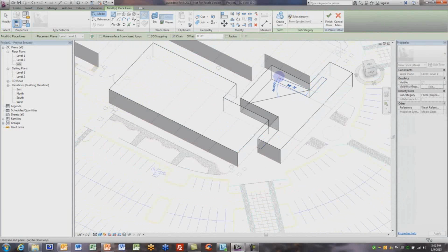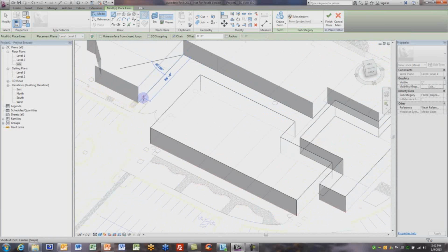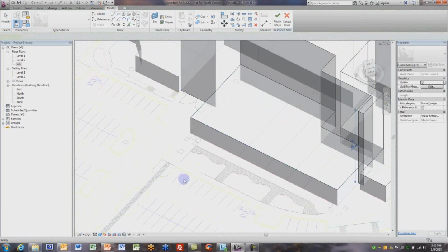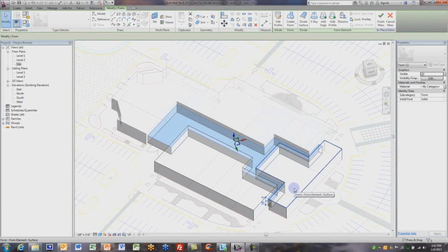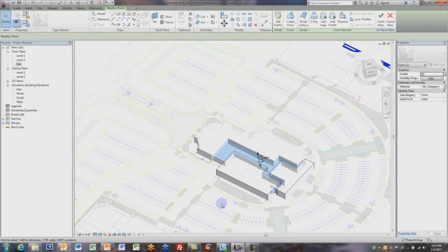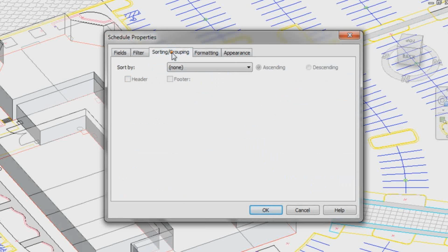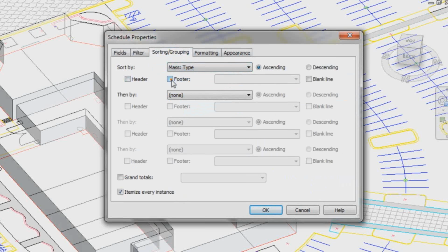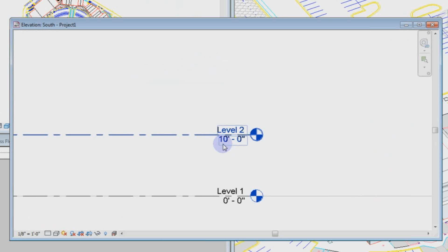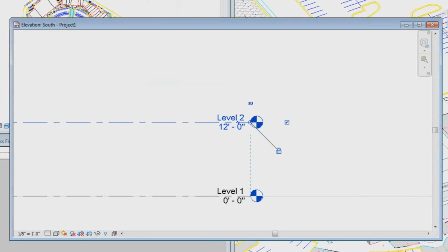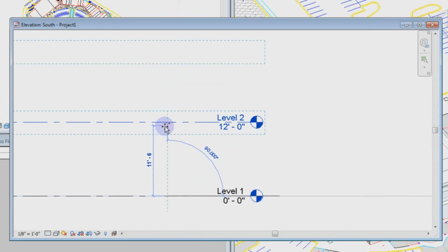This is a retail development, so every inch counts for the landlord because they charge rent for every square foot of the building. Again, this is not rocket science. It's fairly straightforward, just point and click, turning the AutoCAD vector data into Revit 3D massing. Same thing, you could do that by scheduling the masses themselves and turn those into valid areas, volumes, and perimeter information. Changing the level to level height is not a problem because Revit is going to take care of that behind the scenes for you.